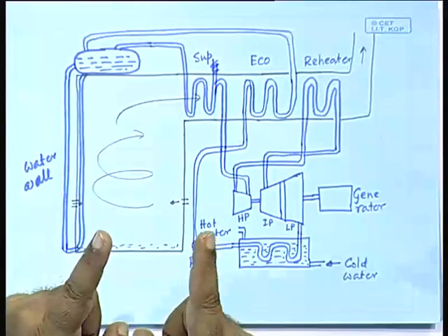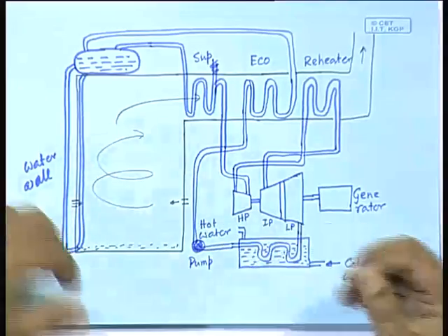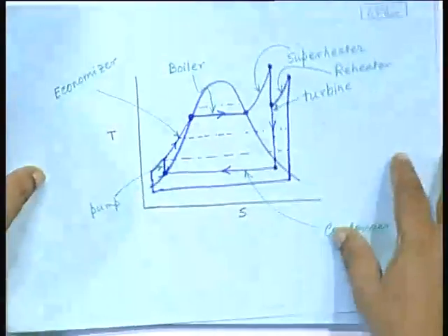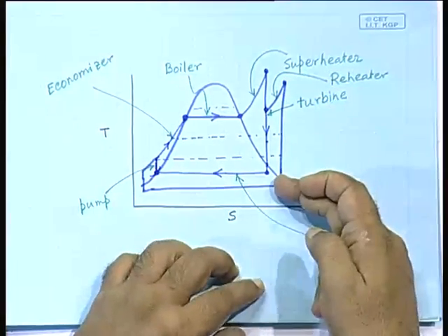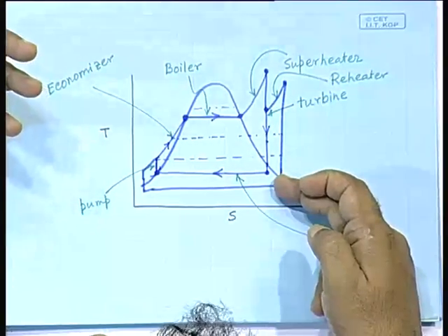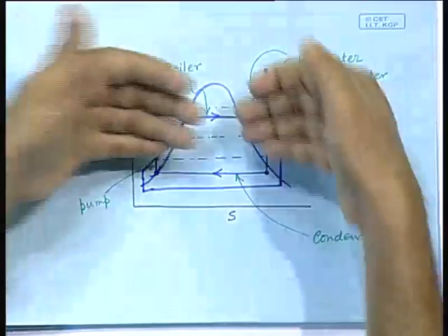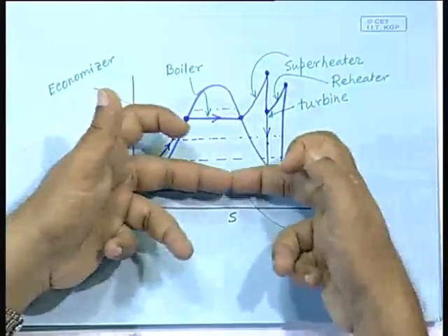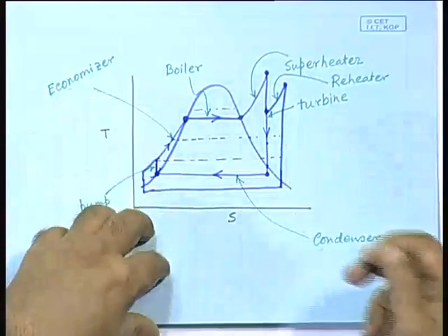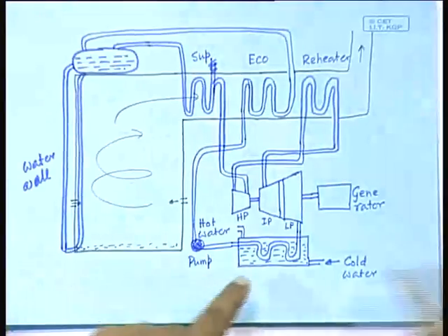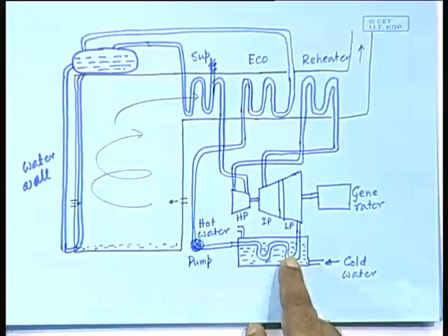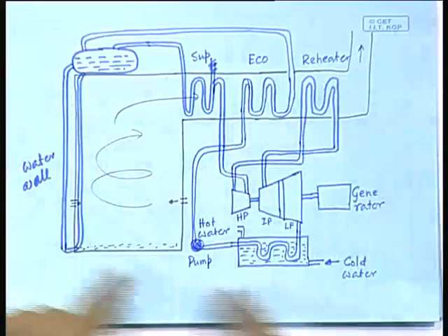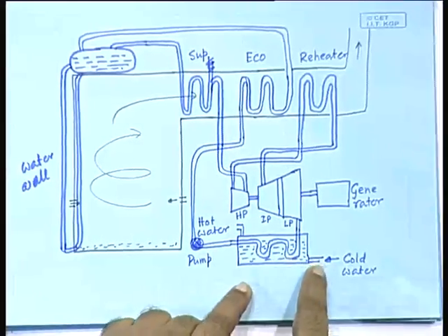No. Another way of improving the total output is to allow it to go into almost a vacuum stage, so that when it comes here it is far lower. So, you add some area here by having a relatively colder temperature here. That is why the overall efficiency of the system improves if this water is even colder.